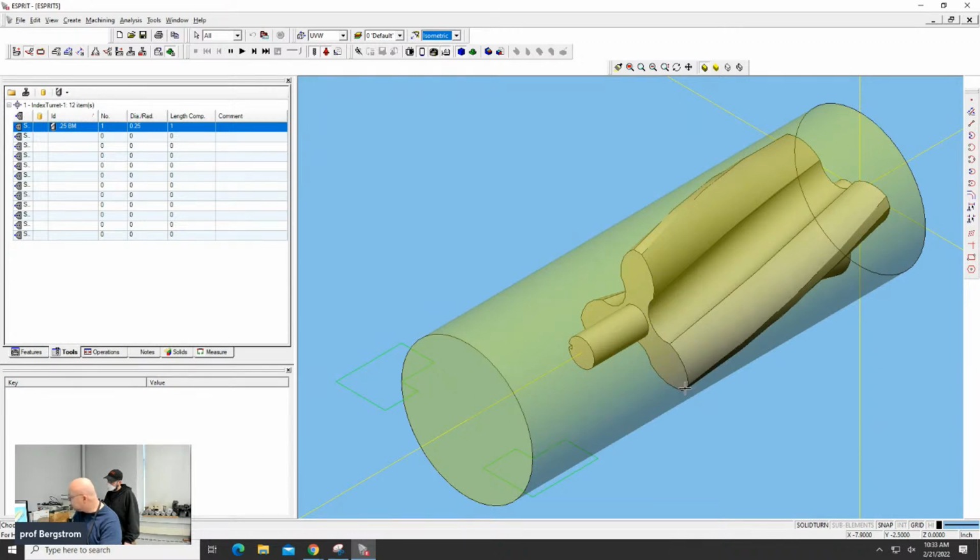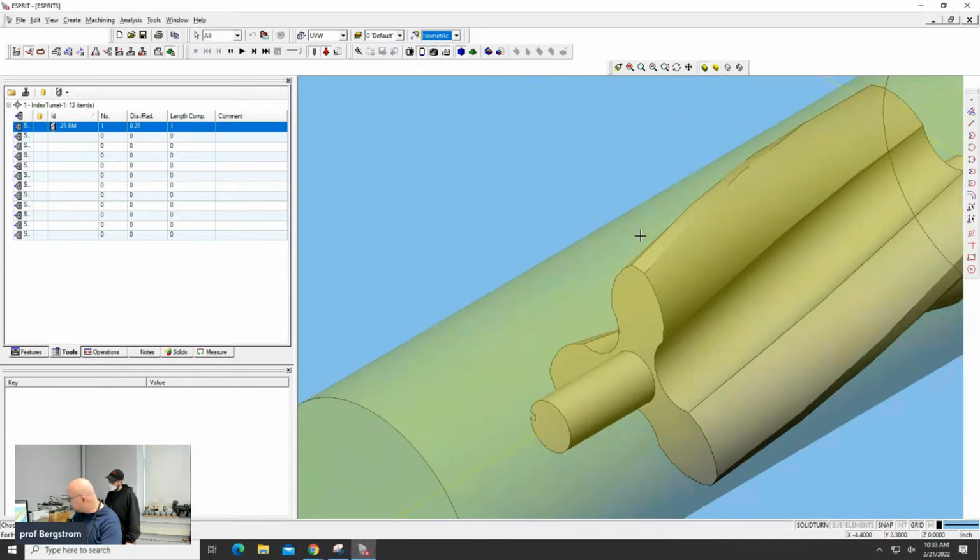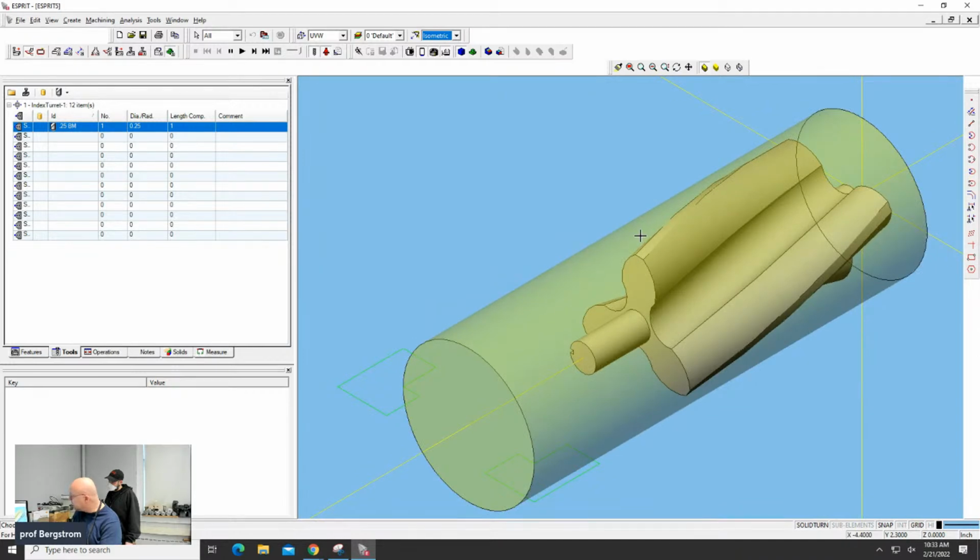So it may not end up being the wrap contouring that'll let you do it. Is it wrap pocketing maybe? Yeah. So I think we've got to make a chain. Do we want to do all the way around or just do one and then rotate? I'd probably end up doing one and then rotating around. Me too. So one goes from this edge. All right, so let's make a chain.